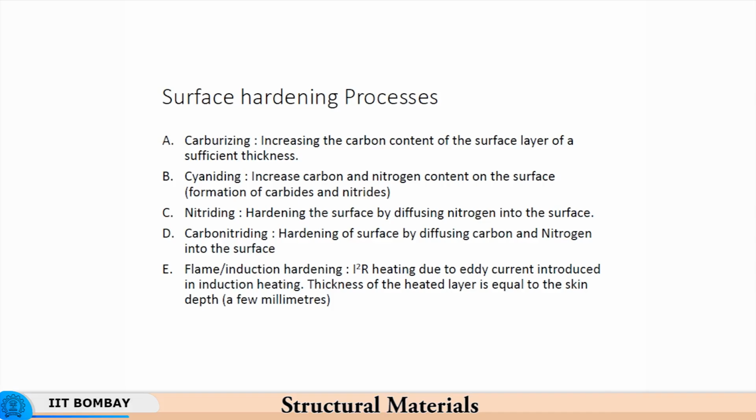Interior might have much less carbon, due to which it might not form martensite, or it might form relatively low carbon martensite. So, the lattice distortions would be very low, but then the hardness at the surface would be very high because the martensite formation took place at a rapid rate of cooling, and therefore you have higher hardness at the surface.